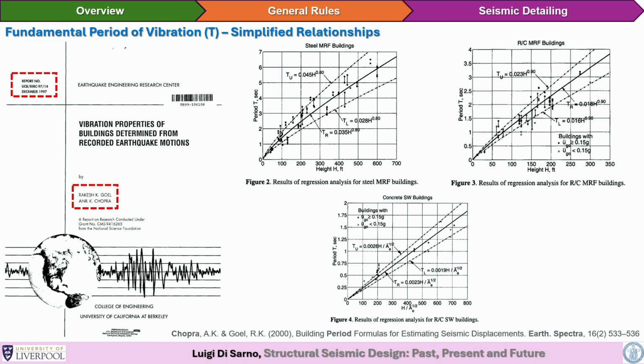And if you search in the literature, there are more and more updated data. This is both for earthquake engineering, but more recently, it has been done also for wind engineering. So if you look into, for example, the response of tall buildings in South Asia, you will find similar plots. These are very important for getting an understanding of the fundamental period, even for vulnerability assessment, because you need to know the period to determine, for example, the likelihood of seismic vulnerability or the wind load resistance.